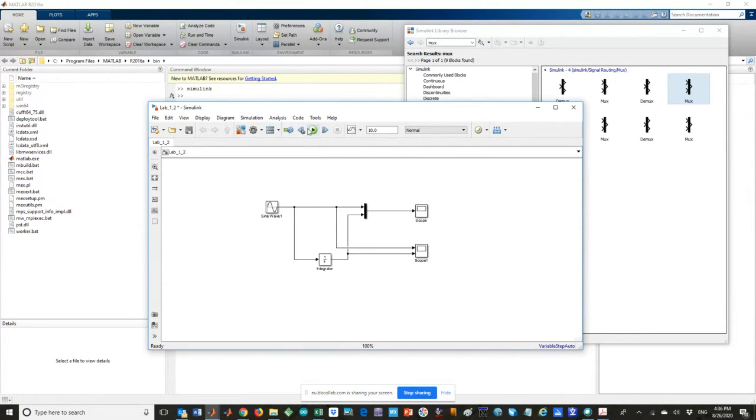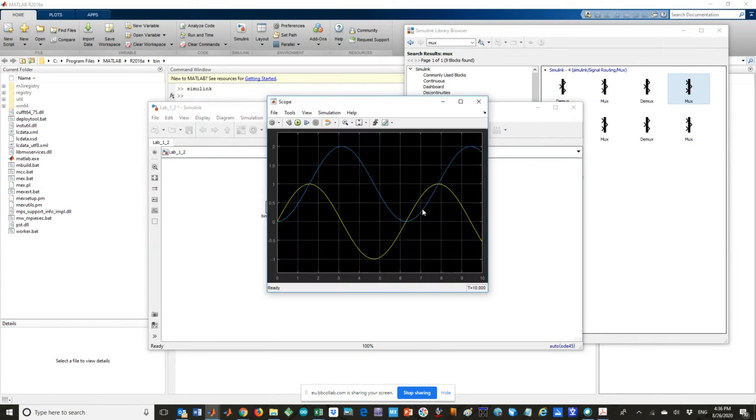To launch this, we click on this run button here. So in run, first of all, Simulink will compile this one. If it's okay, it will start simulating this. Yeah, I think it was simulated. Now, if I double click on this oscilloscope, this will show me. So just click on this because